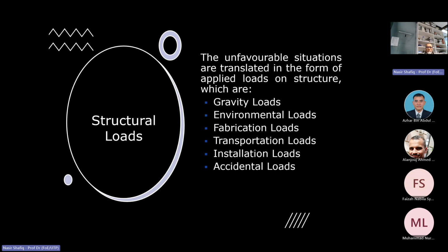So it is not only after the design phase, as I have given you the example, right? When there is corrosion, 20% corrosion, we cannot put the 200 bar external load being applied on the internal wall of the pipe by the flowing gas, right? So we have to limit the load to 180 bar as a new evaluation, or either we have to repair and maintain if we have to apply 200 bar.